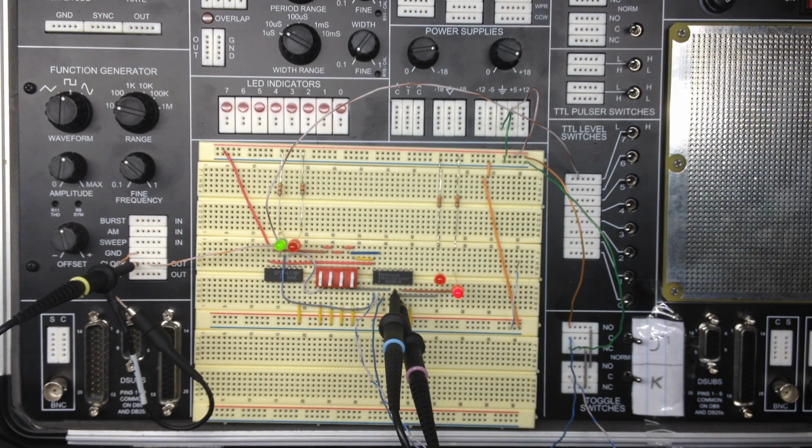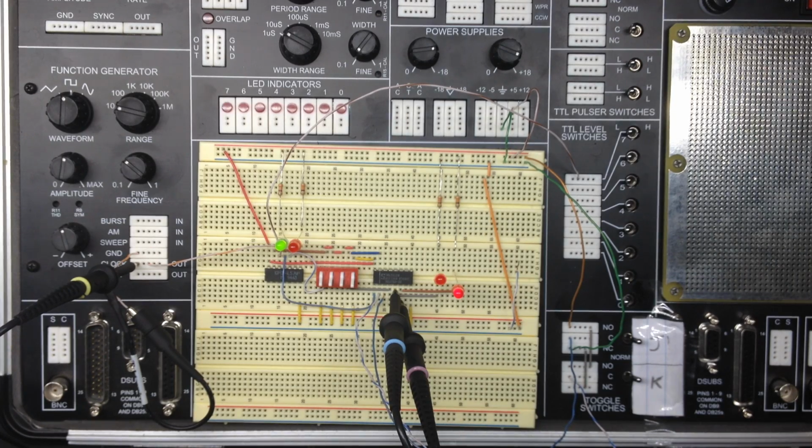At the moment, we're receiving about a 1 Hertz input from the clock going into the circuit. The 74LS74 IC is to the left. The LEDs that are directly above it, the green that is currently lit and the red that is not lit right next to it, represent Q and Q naught respectively. To the right, the 74LS112 IC has 2 LEDs to its right. The LED to the left is representative of Q, and the LED to the right is representative of Q naught.